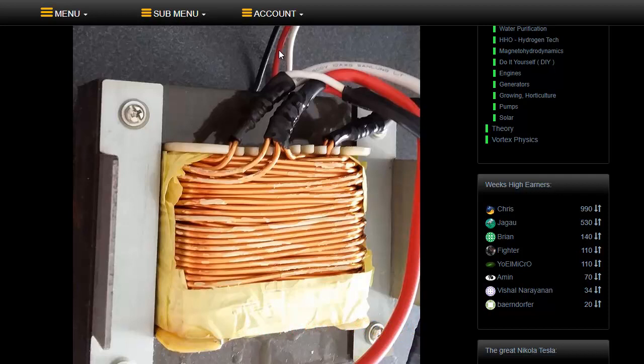So in an ideal transformer, what I'm trying to say is the ampere turns on the primary coil would be equal but opposite to the ampere turns on the secondary coil. So we're talking ideal transformer, lossless. We're not considering losses at this stage. So in a lossless transformer, the ampere turns, or the magnetic force on the input, is the same as what the output is. Okay. Now, how do we get around that?